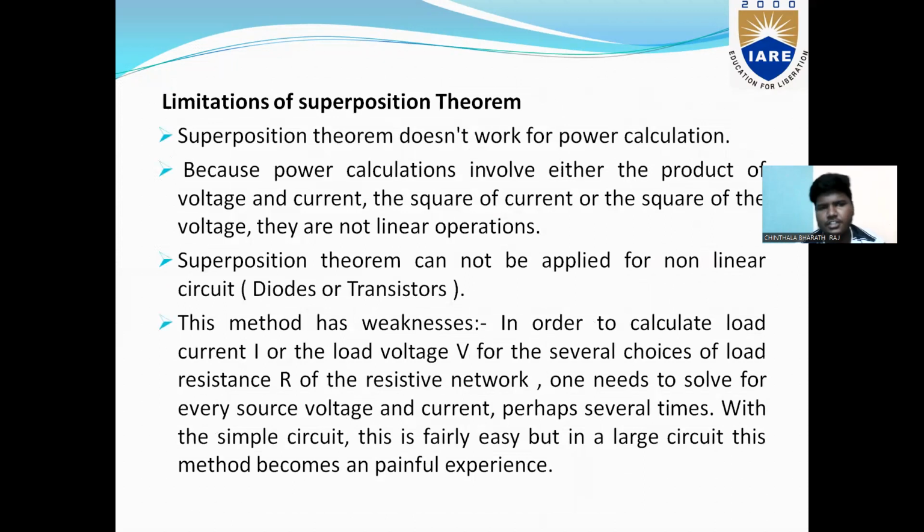And now the limitations of the superposition theorem. The superposition theorem does not work for power calculation, because power calculations involve the product of voltage and current, or the square of the current or the square of the voltage, and these are not linear operations. The superposition theorem cannot be applied to a non-linear circuit.